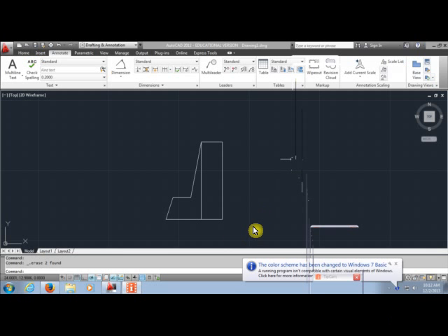And say OK. And you can see immediately that the cursor has changed shape to show that we have an alignment now. And then remember that I want to turn ortho on, because if I don't have ortho on, it's not going to keep me along the planes that I'm discussing. So I'm going to go in and go back to home. And now I want to start drawing the isometric view of the same object that I just created.